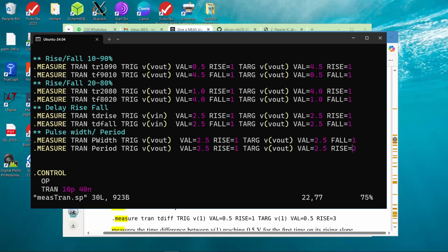Okay. Because what you have done so far, that's hard coded. Now, if I say, oh, change the VDD from 5 volts to 3 volts, then this whole thing will collapse, right? It will not work because you have done everything hard coded. So we'll change. So we'll copy this file. We'll keep this one, copy this file and do it as parameters and variables and do that.